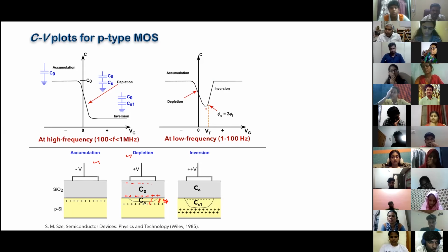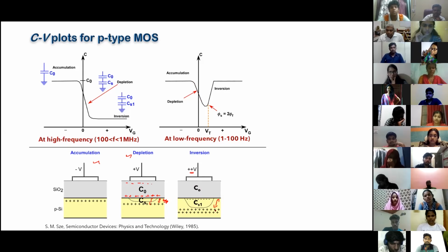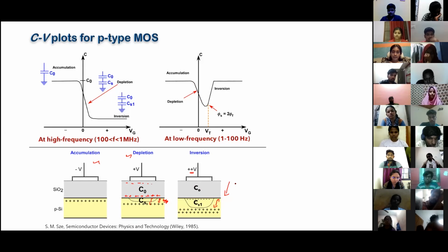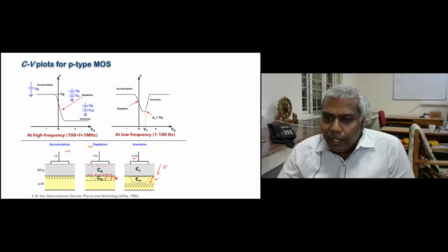So you are increasing the voltage again further. Now, what will happen? Not just this depletion takes place, okay? The first thing is that because of the heavy positive voltage, the thickness of the layer will be really high. But that is normally happening there. In addition to that, because a heavy electric field will be set up there, that heavy field will make an instability in the semiconductor, and it will generate thermal electrons.